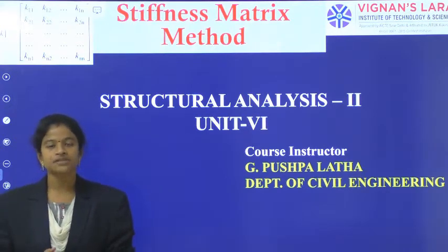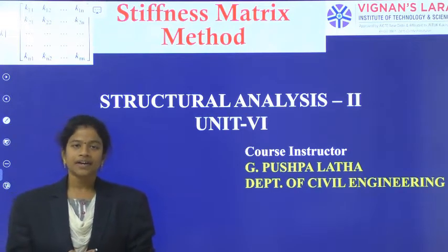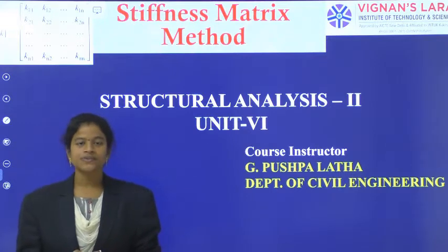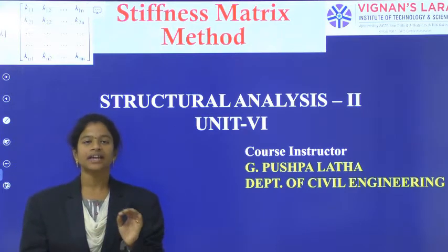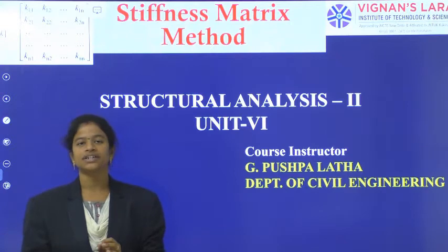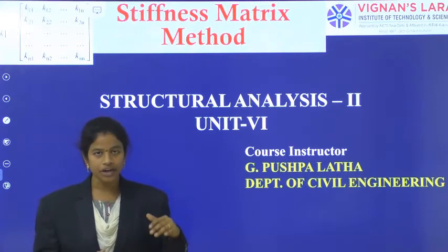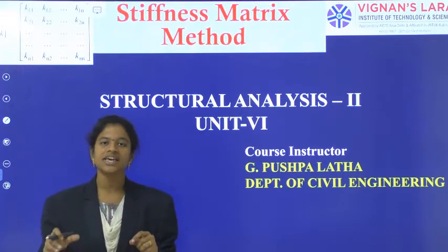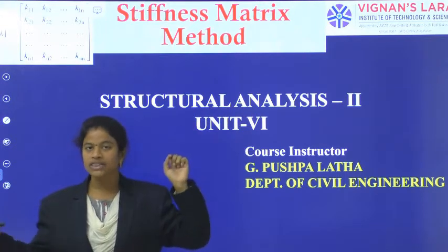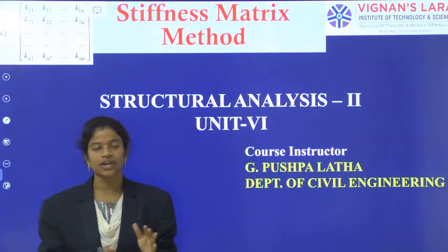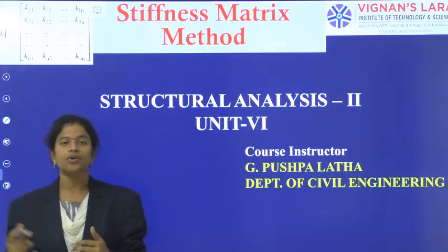Now coming to the stiffness matrix method, which is our next method of analysis using the matrix concept. For analyzing any indeterminate structure using the matrix method, as we have more unknowns when going for multi-storied structures, the mathematical concept of matrices is involved and a number of equations can be solved at a time. Due to the application of load at some point, its influence on another coordinate can also be observed in the same matrix. So many analyses can be done using a single 4 by 4 matrix, where 4 equations can be solved at a time.